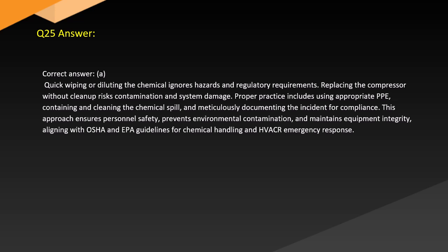Answer. Correct answer: A. Quick wiping or diluting the chemical ignores hazards and regulatory requirements. Replacing the compressor without cleanup risks contamination and system damage. Proper practice includes using appropriate PPE, containing and cleaning the chemical spill, and meticulously documenting the incident for compliance. This approach ensures personnel safety, prevents environmental contamination, and maintains equipment integrity, aligning with OSHA and EPA guidelines for chemical handling and HVACR emergency response.